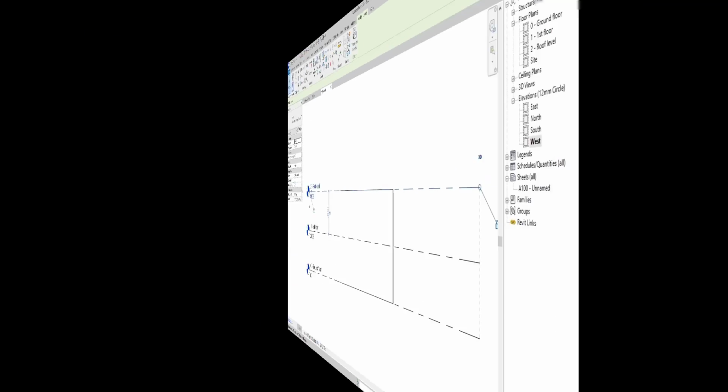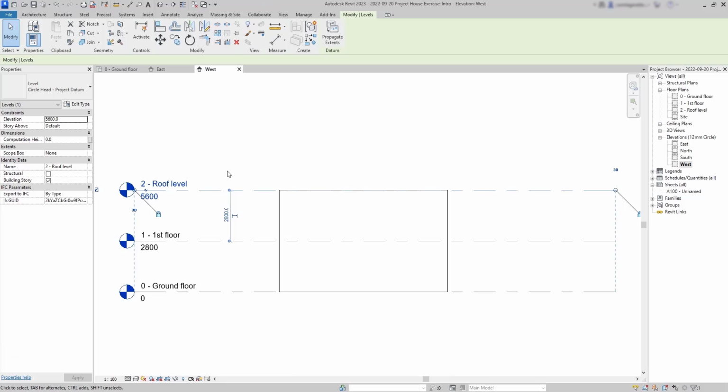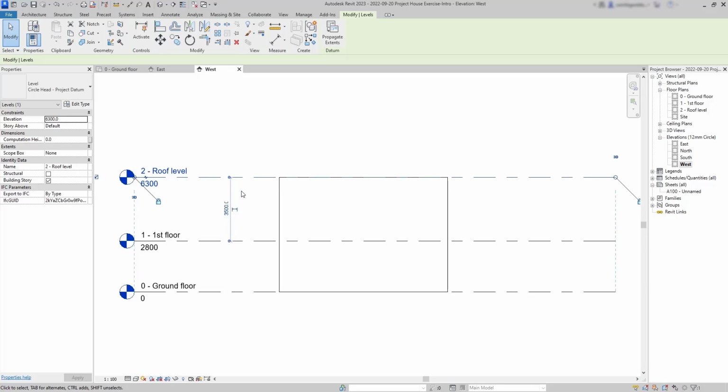So, a great advantage of using top constraints in walls is that later, if I decide to change the position of the levels, the walls' heights are automatically readjusted.